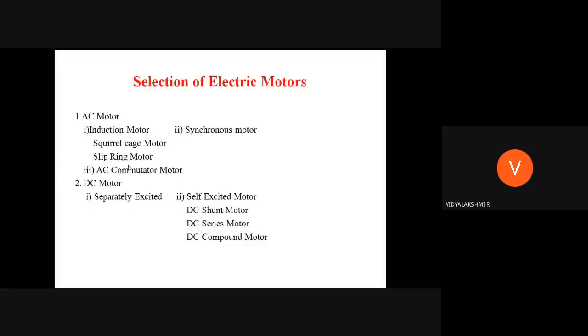I already said poor power factor means we have moved away from the unity power factor. Unity power factor means my efficiency will be good. If it is poor power factor, my efficiency will be affected. So what will happen? My output will be very less. If the efficiency is less, we won't go with this type of motor. So we probably use this type of motor for low power or low speed applications, where I'm using this type of motor to drive fans, pumps, conveyors and lathes.